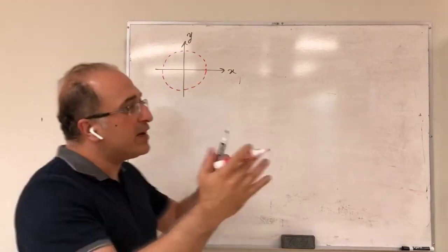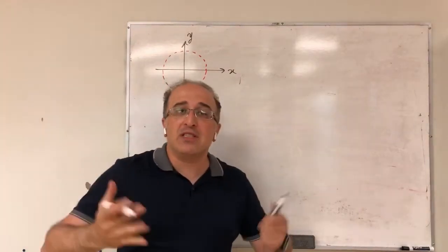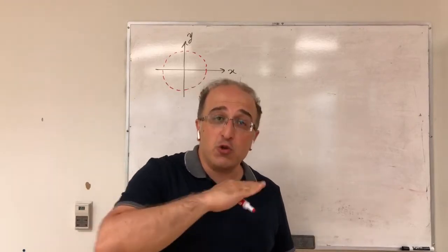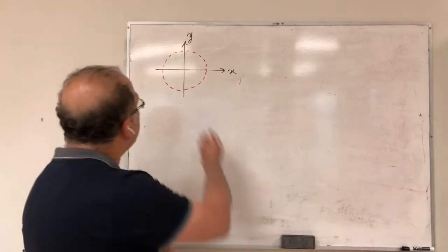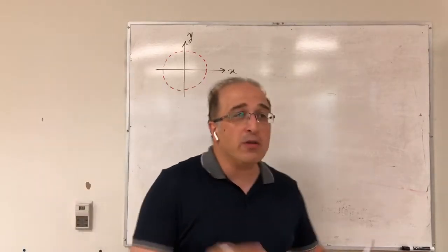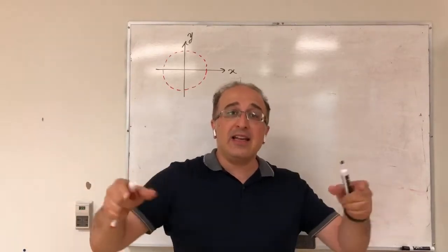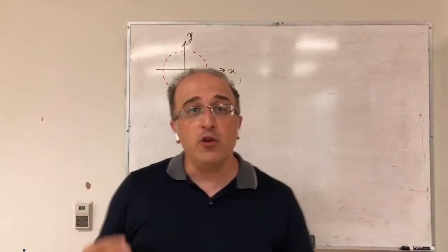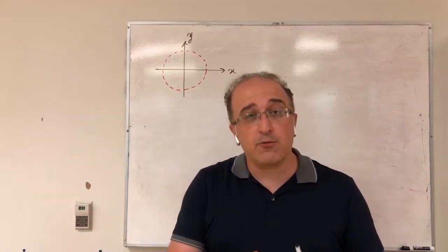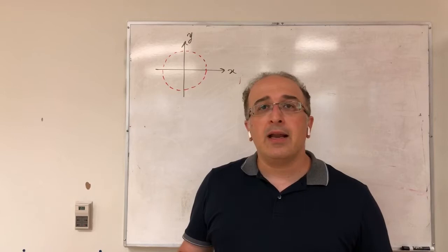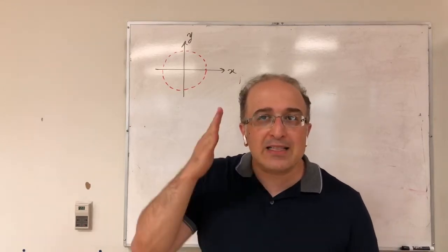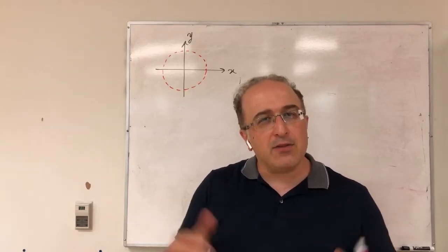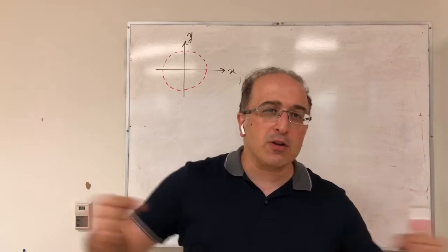So essentially, everywhere that you go on the XY plane, you see the same thing. So that would be the radiation pattern, but a 2D cut of the radiation pattern. And if you see something like that, you would say, oh, this radiates in this plane, essentially the same. And you might like this type of radiation pattern for some application. For example, in applications that you don't know where exactly you want to radiate. For example, in cell phone applications, you don't know exactly where you want to receive your signal or transmit.